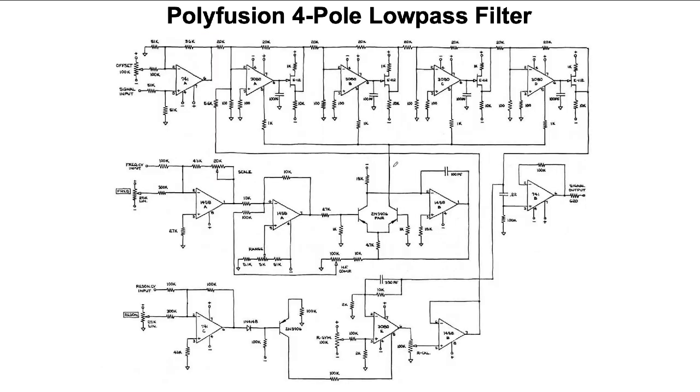One thing we should be cautious about is that the currents that I was plugging in there are currents for one of the OTAs. The transistor generating the current in that circuit needs to generate actually 4 times that current because that current is being shared by the various OTAs.